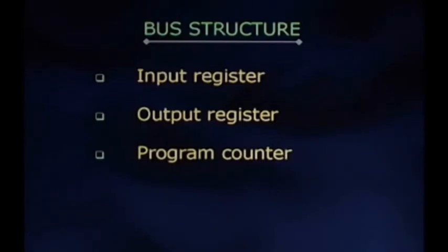The next register is the program counter. The program counter is a shift register used to store the address of the next instruction to be fetched and, of course, executed later. It will have the facilities to clear the register to 0, to increment the register contents and to load the register from some other source.